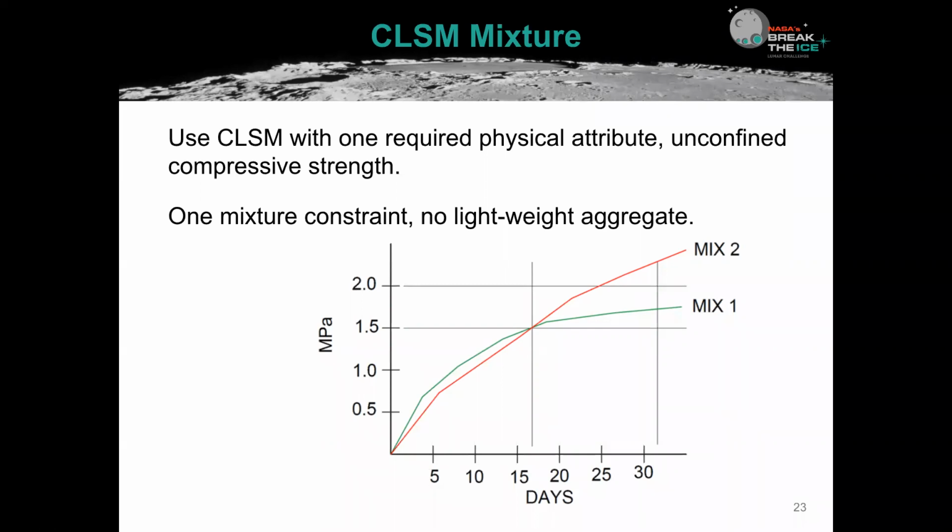As soon as you perform that test and you're at 1.5 or above, you can begin your excavation. The image here is to show you that you probably want to spend some time playing with this mixture to make sure it doesn't have an aggressive strength gain with time.